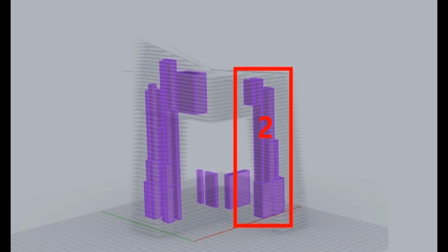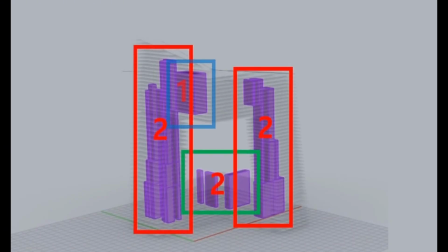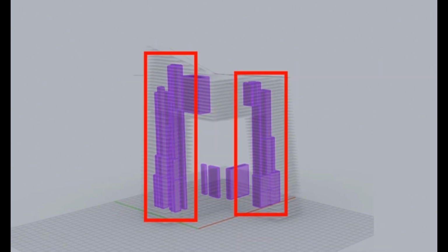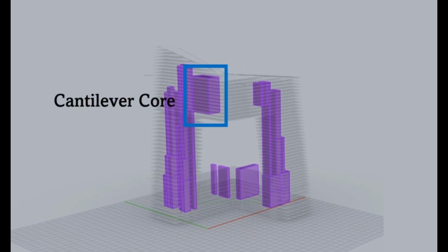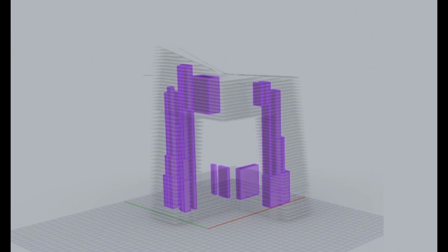As a result, 7 vertical multi-cores with different heights were placed in the CCTV building. In particular, the tower core, bottom core, and cantilever core were properly placed, respectively, as the core is the main factor supporting the load applied to the overhang structure.